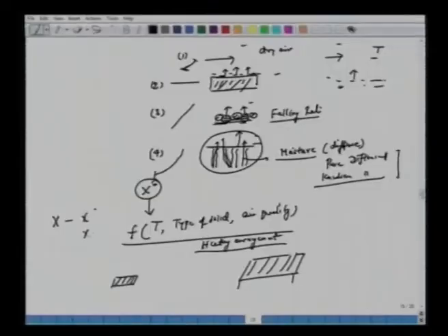moisture and unbound moisture, free moistures. Here also you have X minus X star, which is free moisture. So X minus X star, or Xc, is your free moisture. So going back to the previous discussions, now we have three curves. One, partial pressure over vapor pressure of pure water versus X. That was 1 kg moisture per kg of solid. There we talked of bound moisture, unbound, free moistures. Remember the curve we have. Second one is X versus time. That's true experimental data for that type of solid and that type of operating conditions.